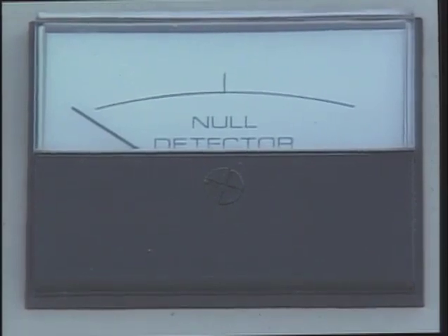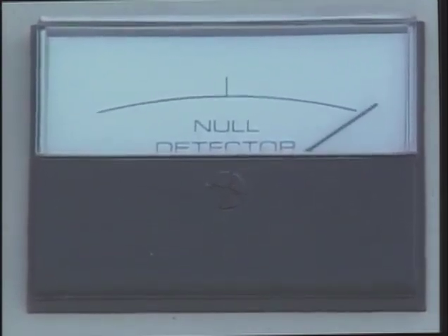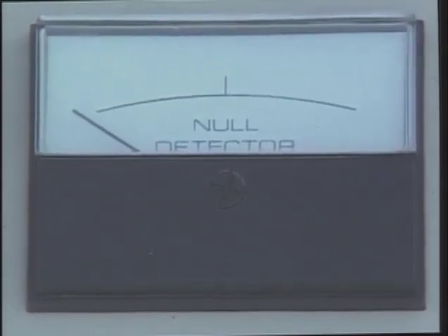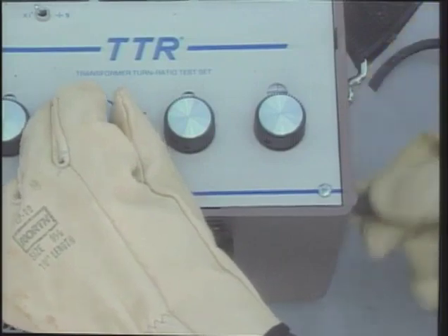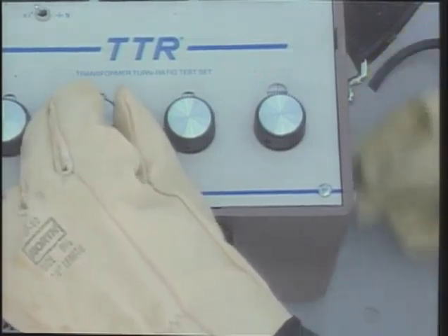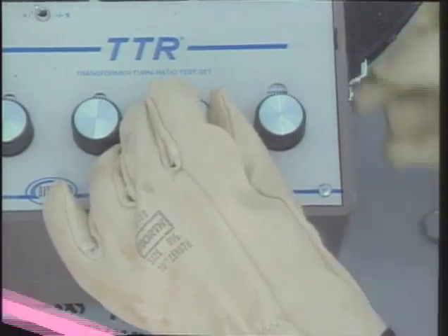If the needle deflects left, the dial is turned clockwise one step while continuing to crank the generator. This is repeated until the needle deflects to the right of null. When the null detector needle deflects right, the dial is turned back, or counterclockwise, one step. The process is repeated with the second dial. The dial is turned clockwise one step at a time while cranking the generator until the null detector needle deflects right. Then the dial is turned back one step. The process is repeated once more with the third dial.